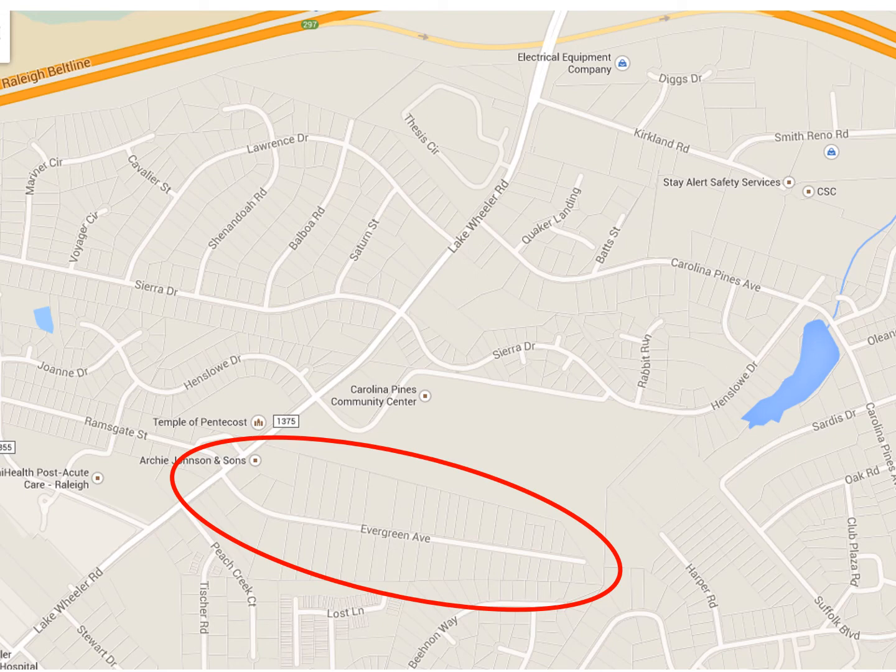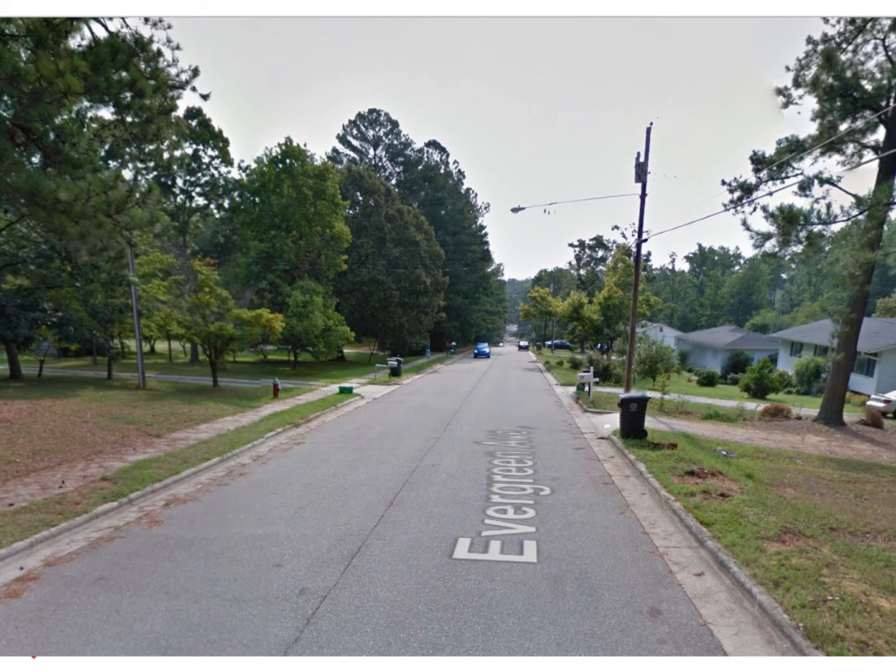So just as an example, this is a street in Raleigh, North Carolina. One horizontal curve at the beginning, and then it's essentially a quarter-mile tangent that doesn't do a lot to discourage high speeds. There's actually some vertical alignment on this as well. So a pretty long section of a downgrade, and then it's flat at the bottom.